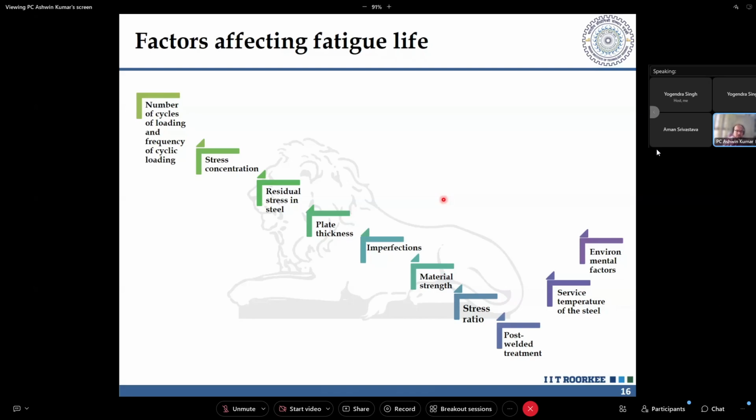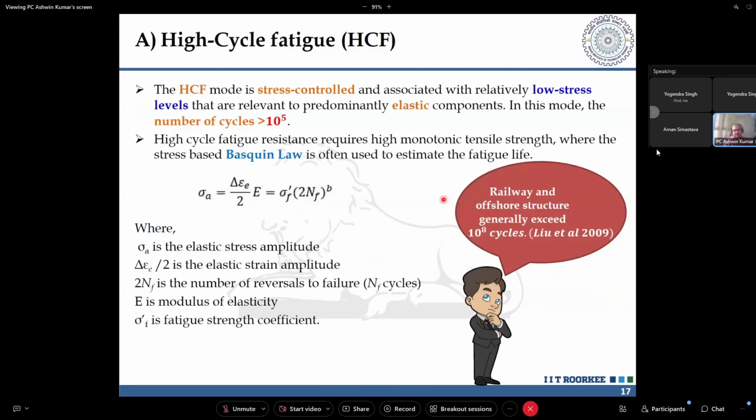But does corrosion affect the yield and ultimate strength and ductility of the steel? Let's look through the slides and understand that yes, corrosion does affect the fatigue strength in a negative way. The fatigue strength decreases, but what all things are we ignoring? Our understanding with respect to structural steel needs to improve so that our steel bridges are more robust in tackling fatigue. Now, in this particular lecture, we'll be looking at only high cycle fatigue in terms of bridges. There is also low cycle fatigue, extremely low cycle fatigue, and ultra low cycle fatigue that come into the picture.